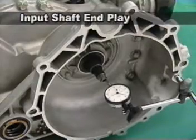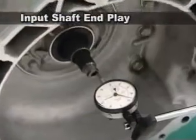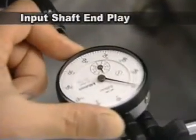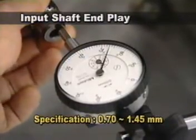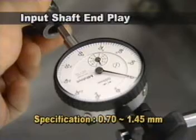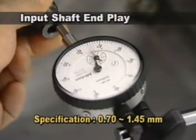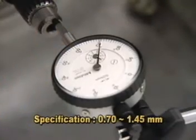First, measure the end play of an input shaft using a dial gauge. If the measured data exceeds the specifications, replace the number 1 thrust washer. Measure the end play before the transaxle disassembly and compare the measured value after assembly of the input shaft.